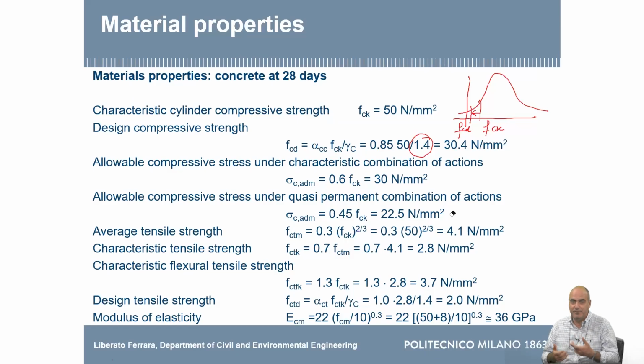It's a matter of making more complicated calculations, because you can no longer say the creep strain is proportional to the elastic and you just have a 1 plus something, 1 plus phi coefficient. You must make nonlinear creep calculations, which I can guarantee you are not that simple. But besides the complication of the mathematics behind that, it's a functional issue. You want to keep the creep strains controlled, because otherwise your element continues to deform, to deform, to deform.